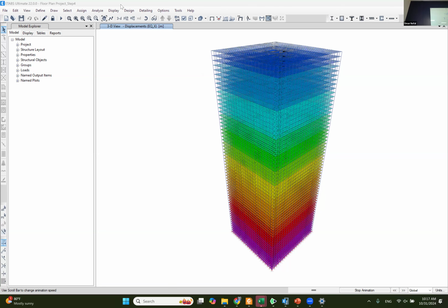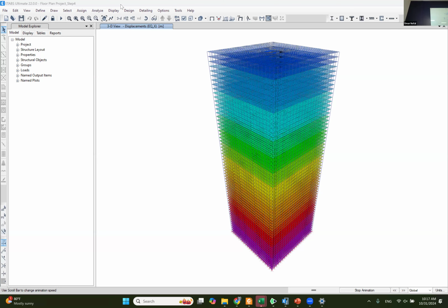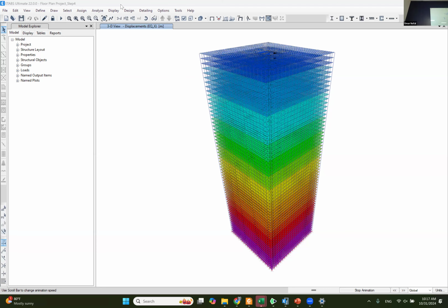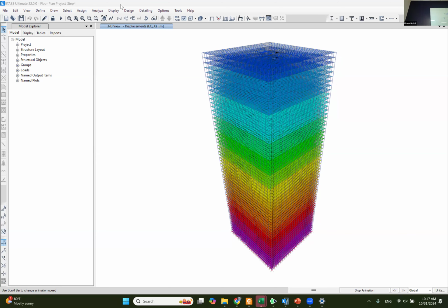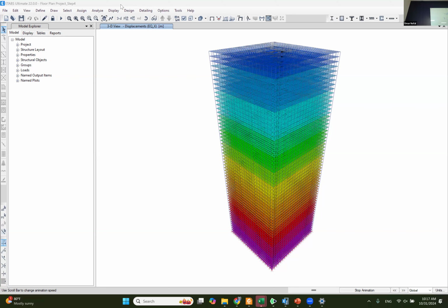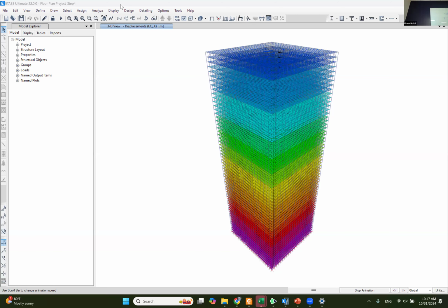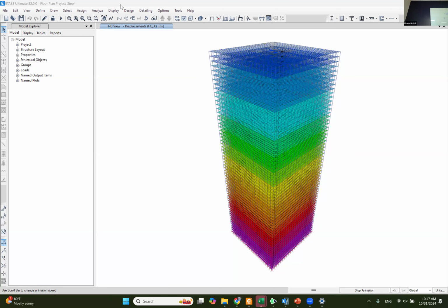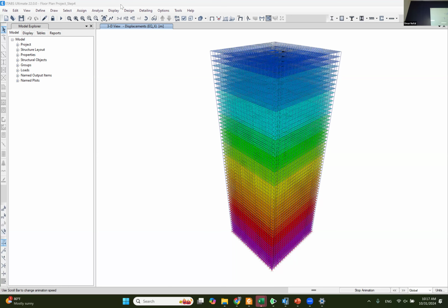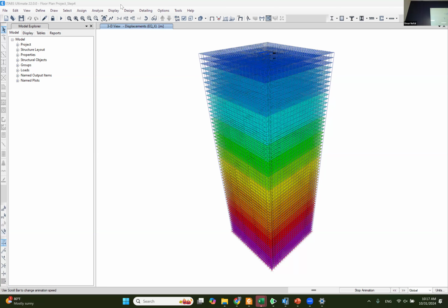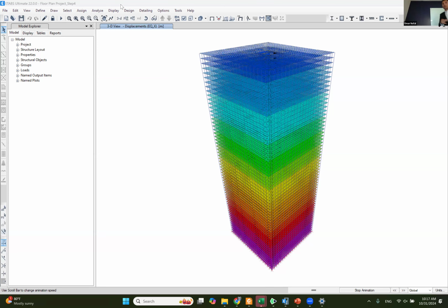One thing: since we are doing tall building analysis, I need to see the profile of the building all over the project. Sometimes people just put the plan view from the top, but when you show me analysis, I need to see the elevation information. I need to see what the building looks like. So when you describe the building, show me the plan and the distribution of the columns, and also a profile of how the building looks. And when you show me the deformation, show the profile and how the deformation looks. That's very important when it comes to tall buildings.